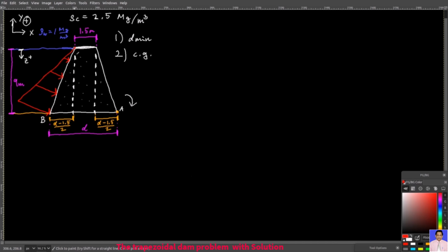Here at this point, the force distribution per unit length is 0 newtons per meter, because your z here is 0 meters, and then here at point B, your wB equals pressure times 8 meters, which is the width of the dam.